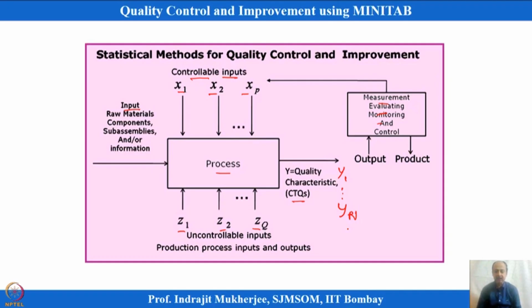So, every time we get outputs, we measure them, and in inspection they measure all critical CTQs. Based on the condition of the CTQs, they will either change the setting condition or keep it as it is. This measurement and evaluation is done by a specific tool known as the process control tool, the statistical process control tool.